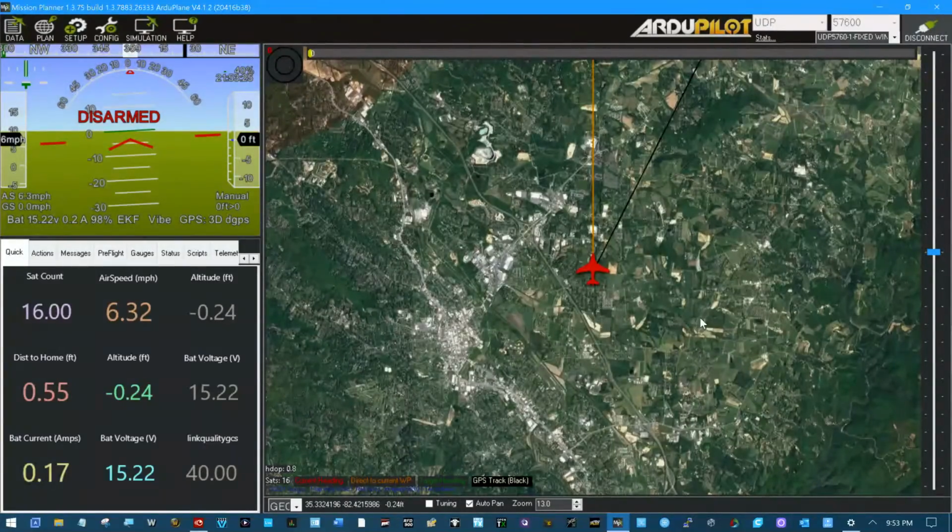Trying to do that, you're going to have an antenna tracker, all sorts of junk. The narrower the beam, the harder it is to target a platform, but it will go a further distance. But straight up, we'll just talk about that. You can put a crosshair or a pepper box antenna on your Crossfire transmitter instead of the horizontally polarized antenna to get that extra range, but then you're going to have a direction.